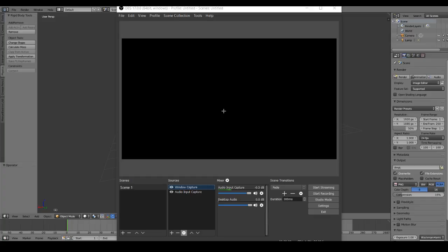So what we have is these vertices that we can move around at our discretion and see how things work. The problem is, if I do something like this, it's going to do that, but that makes it harder on the computer to render because it still thinks this is a flat face. So the best way to remedy it is we select all of them, and by the way, we can select vertices, edges, or faces. Right here I'm clicking faces, clicking edges, and I usually stick with faces. So first thing I'm going to do is subdivide it.